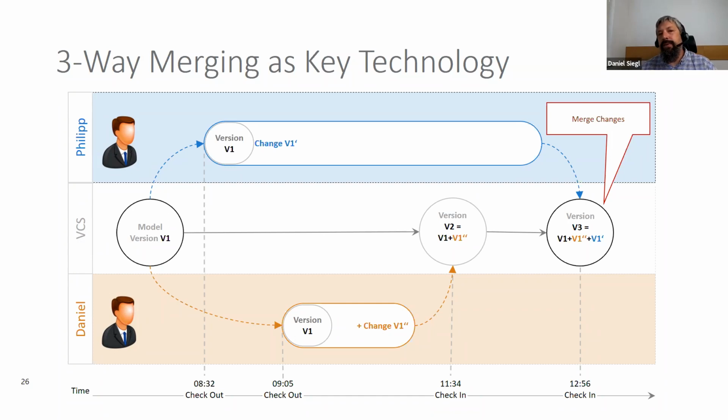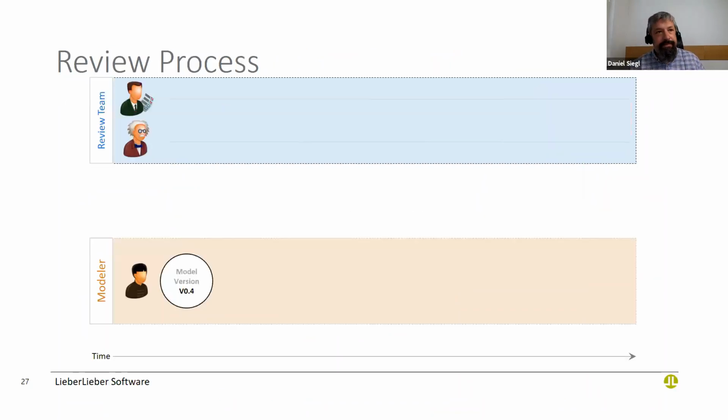It's something super normal. The alternative that you can do with Enterprise Architect standard features, you can use a pessimistic version control. Pessimistic version control means you have to ask for the permission to get a part of the model under your supervision. You change it and you have to return it back. Nobody else can change it in the meanwhile. So this optimistic version control approach is also one of the enabling technologies for any type of agile MBSE.